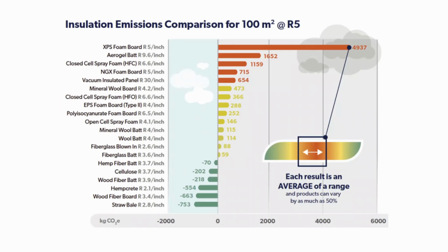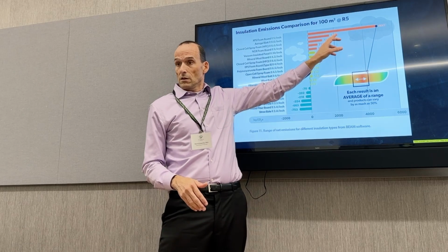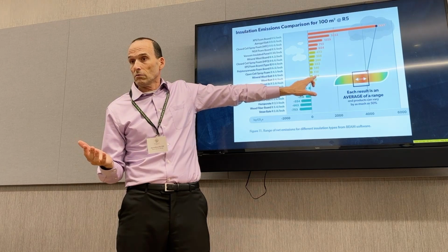And what's the difference besides an E and an X? XPS is extruded polystyrene and EPS is expanded polystyrene. It's a different manufacturing process. They serve the same function. You can use them under grade, you can use them as a high PSI mix. They cost about the same. I have no idea why people use XPS, when EPS is a much better product with the same functional effect.